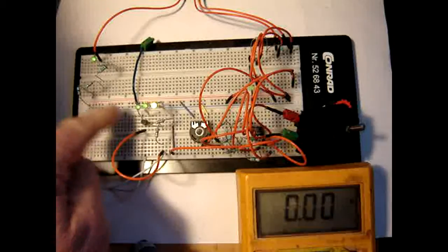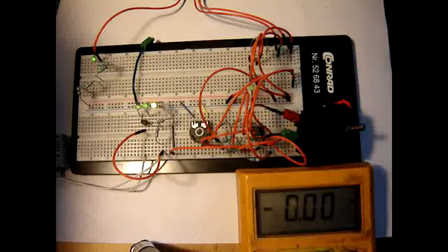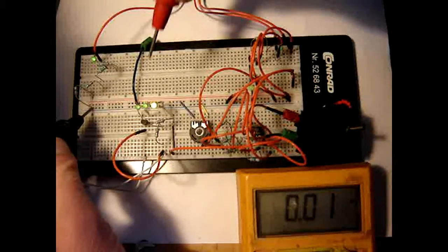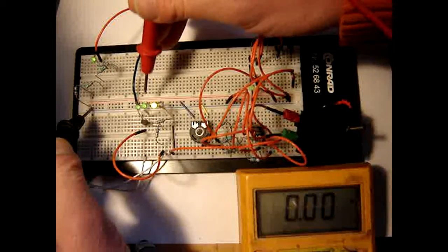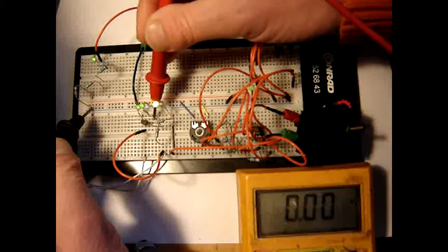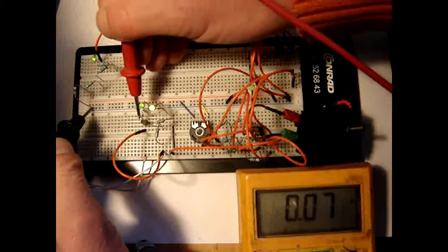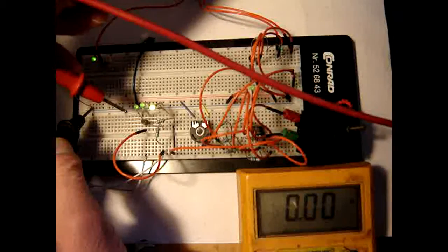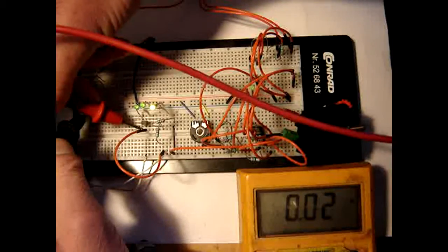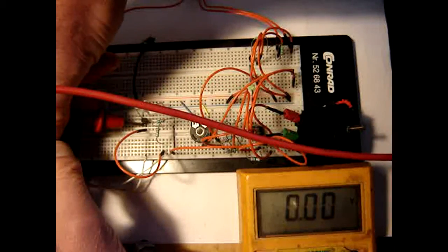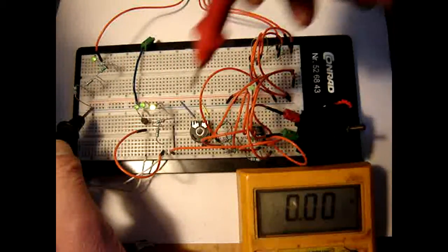is that here are voltages as well. So let me measure those. It has been a while, so let me just track those. If I measure here, this is 1.8, and at this side 1.8, and the entrance of the transistor shows 0, which is hardly possible.